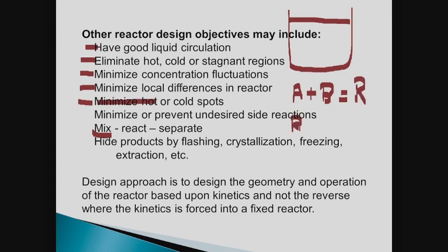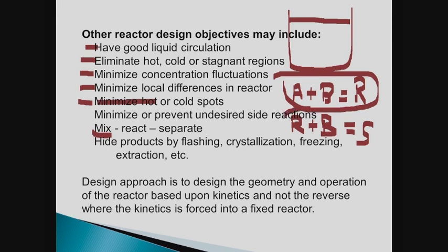R plus B again gives you S, and S is a waste. Not only that, it's carcinogenic. So in such a situation, you want to cause this reaction to occur and prevent this reaction from occurring. So your reactor design, and that's what we're talking about, is to, again, maximize this reaction, minimize that reaction.